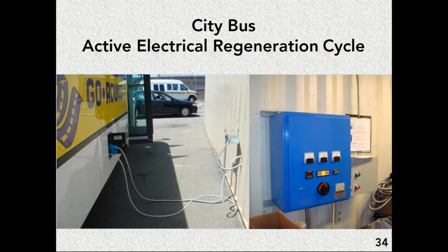So Randy, we also got a question about emergency backup generators, and this would be another situation where you could use this kind of regeneration, because a lot of times when they do their exercises, they're only running for 10 to 15 minutes unless it's a load test. So the person that asked the question pointed out the engines typically don't get hot enough in that scenario to regenerate. So that is a case where you could use active regeneration. Yeah, you might have to, actually. Whether you use plug-in or not is another story. This is just one choice.